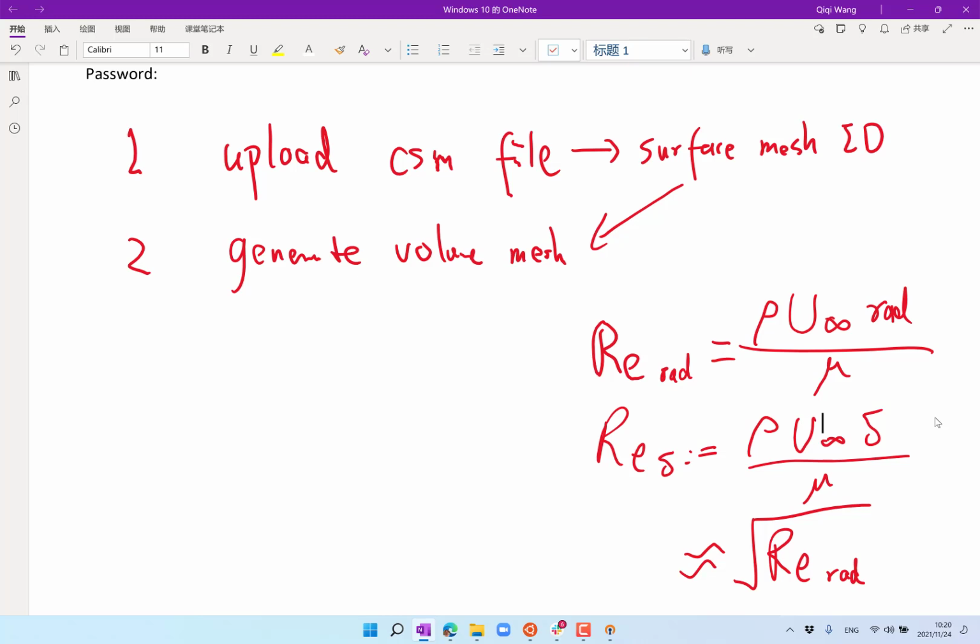Your square root, what function is that? Is that relationship something that I should recognize? I think if you review our laminar boundary layer discussion, right, we did a dimensionality analysis saying that as the boundary layer gets thinner and thinner, the effect of the viscous forces goes like the square of the thickness. If you remember, there is one effect that makes the viscous forces larger.